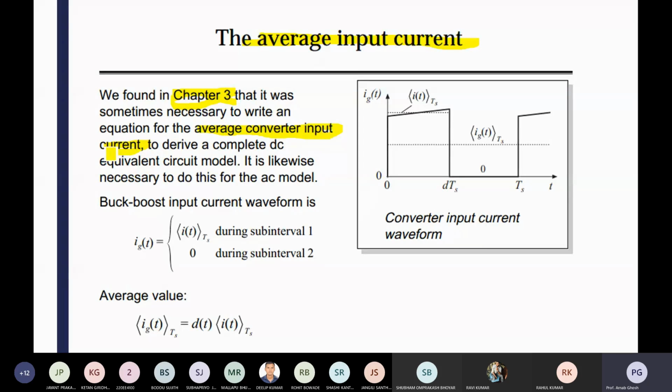That topology decides the steady state nature of the converter dynamics, and the controller decides the transient behavior. So the control circuit is also important for controlling the converter and for the transient response of the converter, while the topology decides the steady state value.